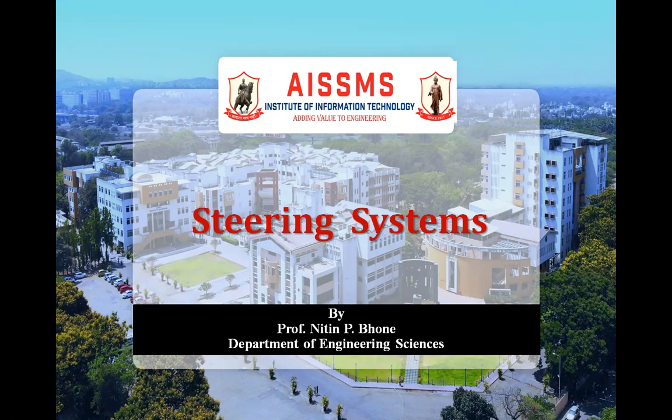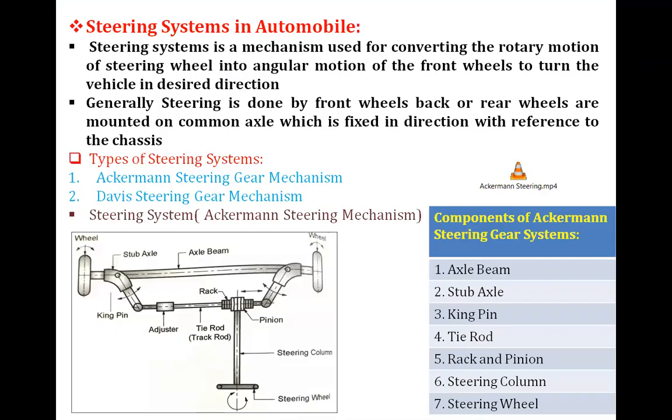Today, we are going to learn about the steering systems in automobile. Steering system is a mechanism used for converting the rotary motion of the steering wheel into angular motion of the front wheel to turn the vehicle in the desired direction. Generally, steering is done by the front wheels. The back or rear wheels are mounted on a common axle which is fixed in direction with reference to the chassis.